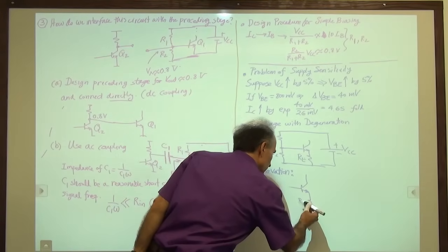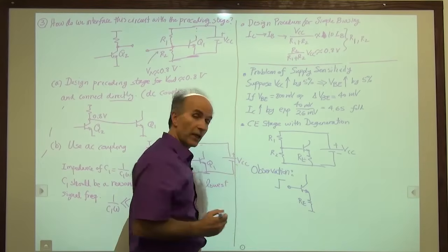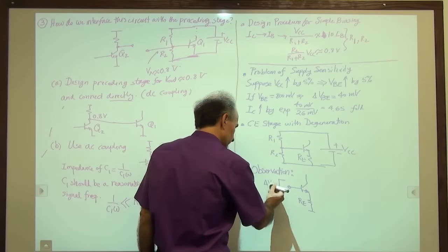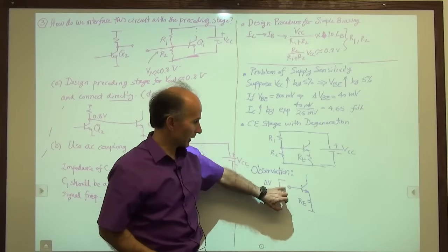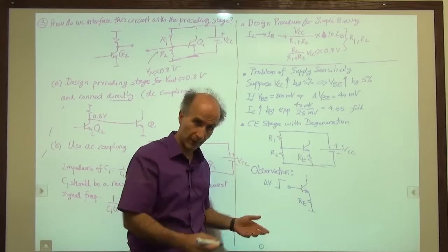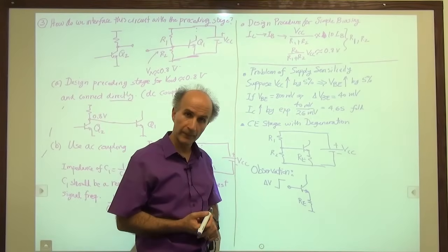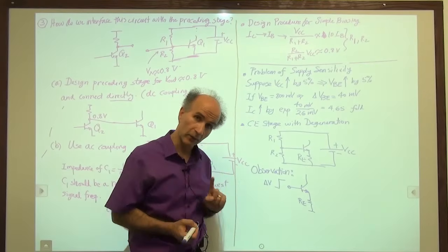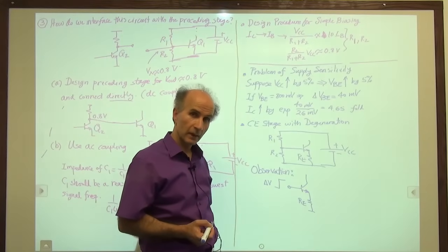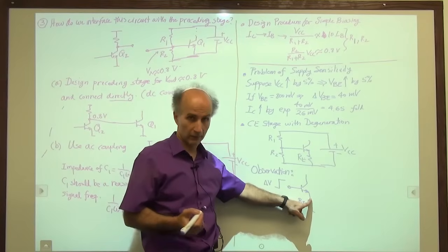We have a resistor here, and we come along and change the base voltage by a small amount, delta V. So let's say the base was sitting at some voltage, maybe 0.8 volts, 0.9 volts, 1 volt or something. And I changed it by some amount, a few millivolts. And the only question I want to answer right now is, what happens to the voltage at this point? Does this voltage go up, go down, or remain constant? That's what we would like to know.